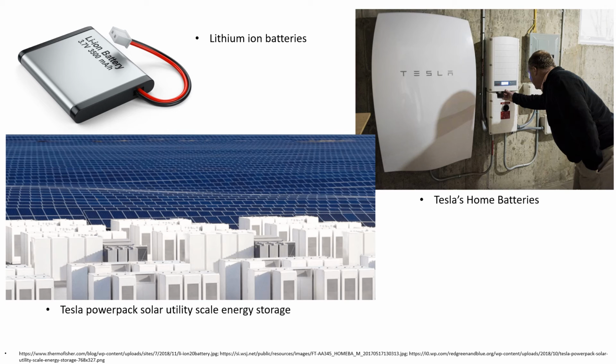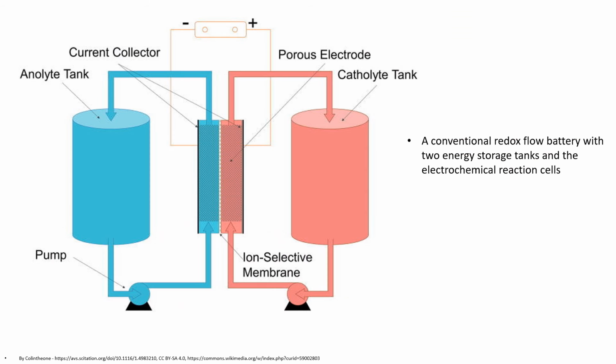As a solution, both chemical-based and non-chemical-based batteries are being researched, involving every single possibility from any element present in the periodic table. One of the workable solutions is flow batteries. A typical flow battery consists of two tanks of liquids which are pumped past an ion exchange membrane held between two porous electrodes. The two tanks contain anolyte and catholyte.